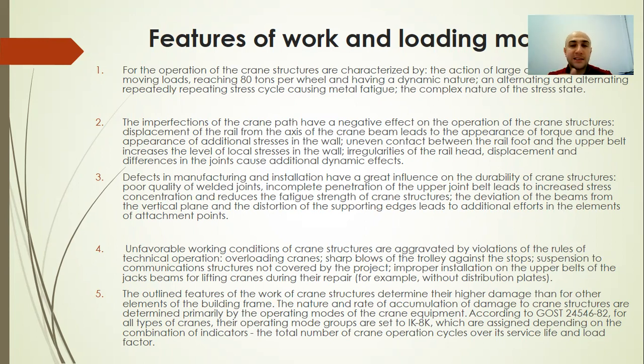So, concentrated vertical crane load, reaching large values, about 600 to 800 kilonewtons, is applied at any point along the length of the beam and leads to the appearance of a complex stress state in the wall at a higher stress level.